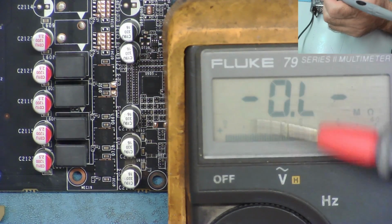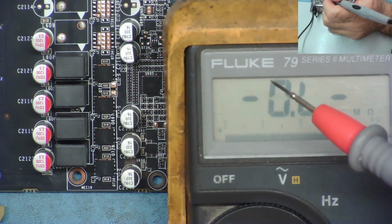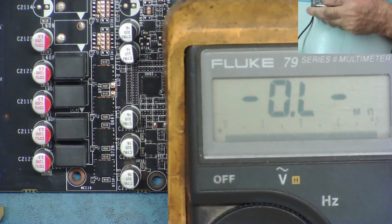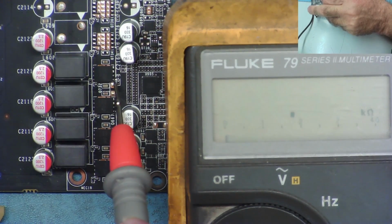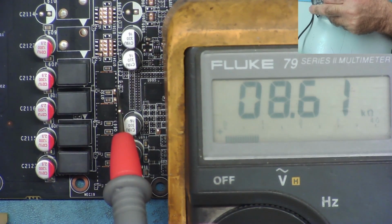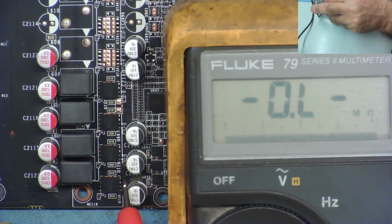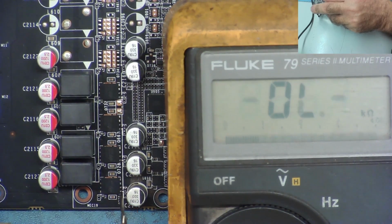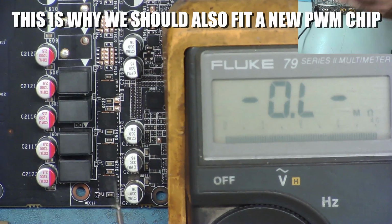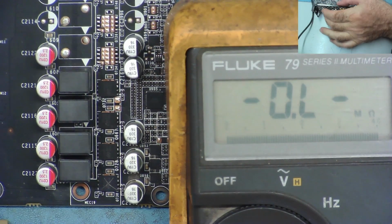But it's possible, although the multimeter cannot see the difference in the resistance here, it might be able to tell us which is the faulty one if we look at the drive signal coming into it from the controller. So let's have a look. This is where the pulse width modulation drive comes in. I've tracked it from the chip. So that's reading 8.6k. That's reading 8.46k. 8.57k. And this one's reading 3.5 ohms. Method 3. Faulty chip. Okay? There's 3 ways to find it.